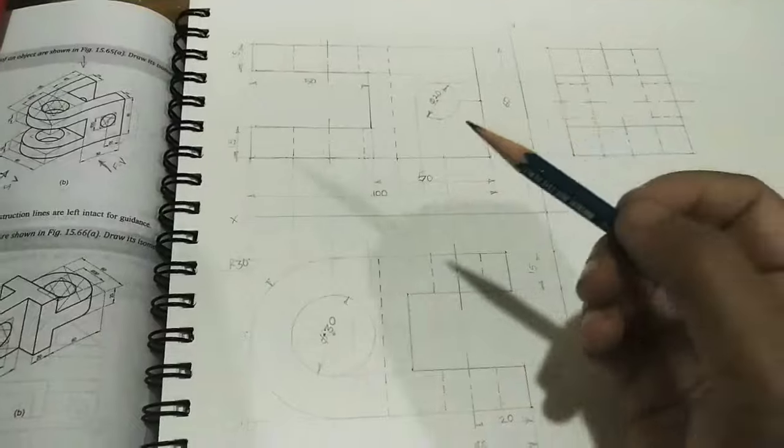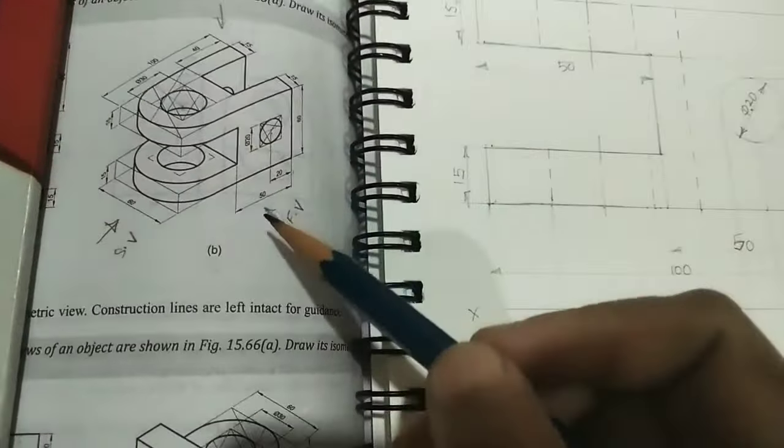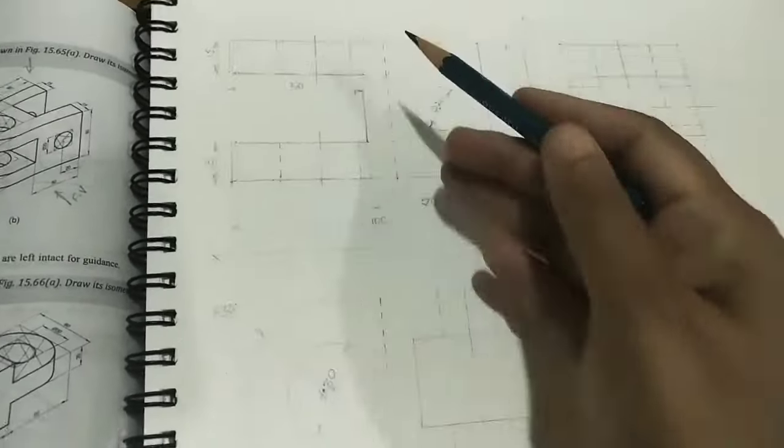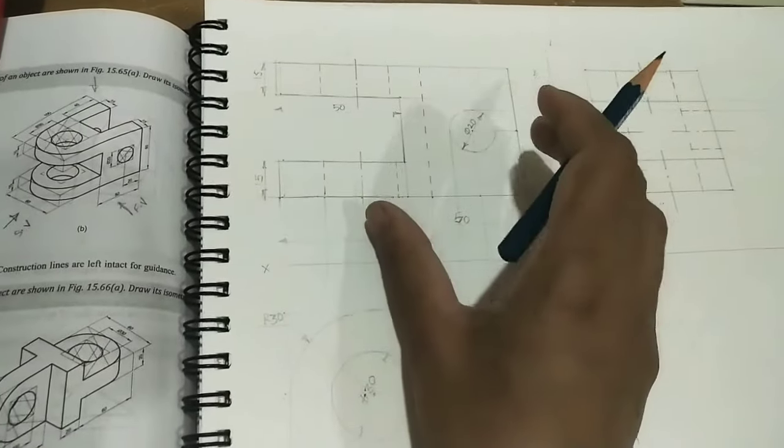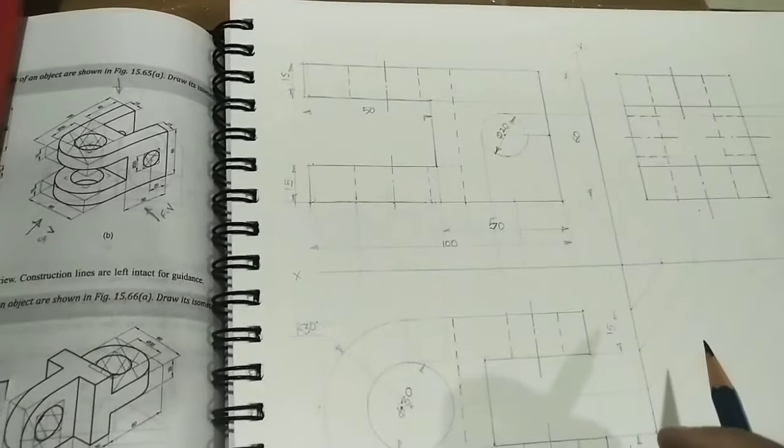After creating all the three diagrams, mark the given dimensions. Here so many dimensions are there. So mark a few dimensions in the front view, a few dimensions in the top view, a few dimensions in the side view. Like that you have to distribute all the dimensions in the three diagrams. No need to mark all the dimensions in only one diagram. You have to distribute the dimensions in these three diagrams.